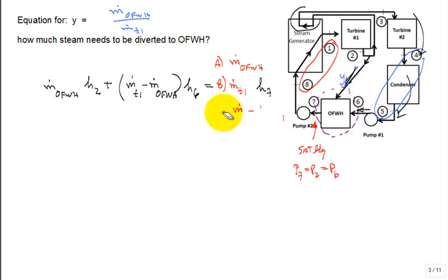What we got is the fluid, and this is the mass flow rate that's going to go into the second pump. That's the mass flow rate going up through 8 into the steam generator. That's the mass flow rate coming out of the first pass in the steam generator. That's the mass flow rate that goes through the first turbine stage. So it was m dot T1 times H7. Does that energy balance look complete?